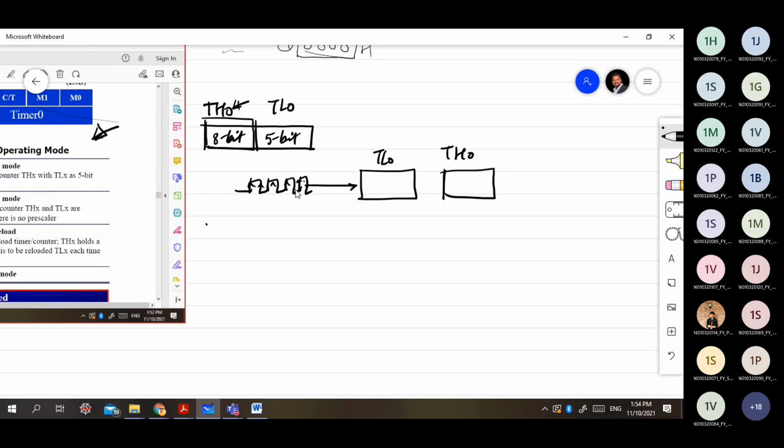Okay. So these are the clock pulses which are reaching the timer. Now the use of this particular pulse is that as each pulse comes, on its rising edge this count will get incremented. First it will increment TL0. Initially the count in both is 0 0. First these pulses will be given to TL0, and after that TL0 will affect TH0, and after that there will be TF. Try to understand what is happening. This is what I am telling you about what happens internally. This is actually not required, but from a knowledge point of view you must know, nothing else.